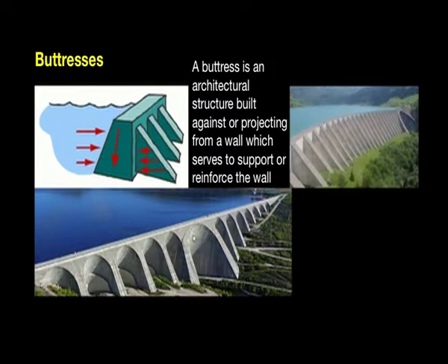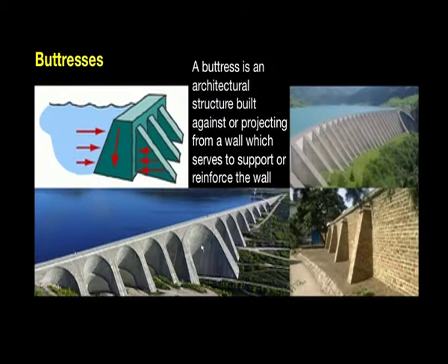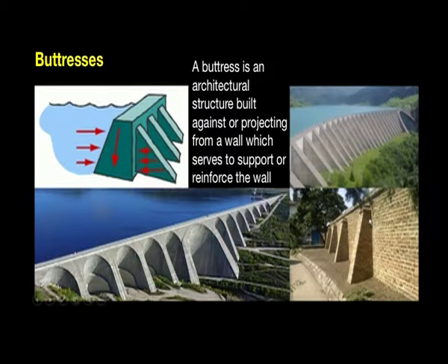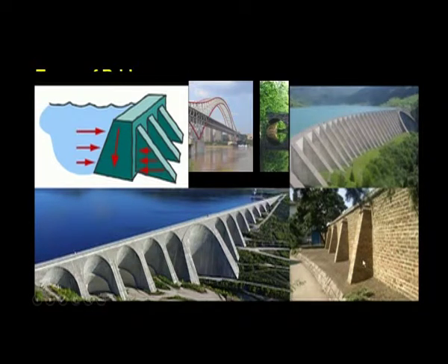And if you think that buttresses are restricted only to dams, think again. If any wall is going to fall, or if there is too much loading onto a single wall, you can find these buttresses. You can find buttresses very commonly in forts, in big palace buildings where the walls are huge and thick. Just to retain the wall itself is a big task there.